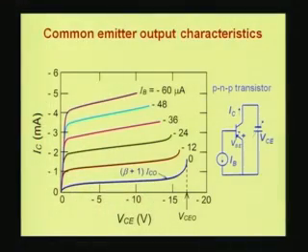Now we have explained how your IB increases. When the IB increases, your collector current goes on increasing. For IB equal to 0, your collector current is beta plus 1 times ICO. Then the collector current almost increases linearly with base current. So that is how you have these increasing currents, and you find here that the slope of the characteristics goes on increasing.